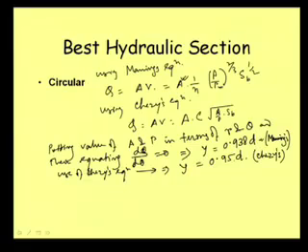And generally a feeling may come to our mind that if a circular channel is a closed channel, and if the channel flows full, then the discharge will be maximum. Of course, if it flows full, the concept entirely changes. It becomes a pipe flow system. We are not talking about open channel flow then. But by open channel flow, if we make the depth equal to 0.95 d, around 0.94 d, then we get maximum discharge, and we should not carry the depth beyond that limit.